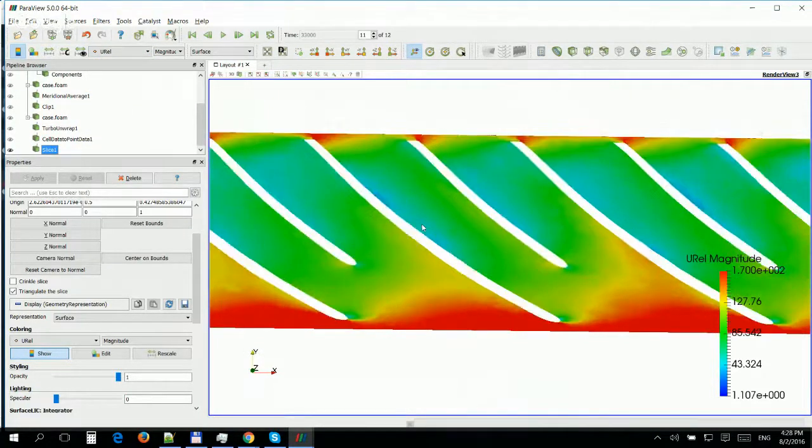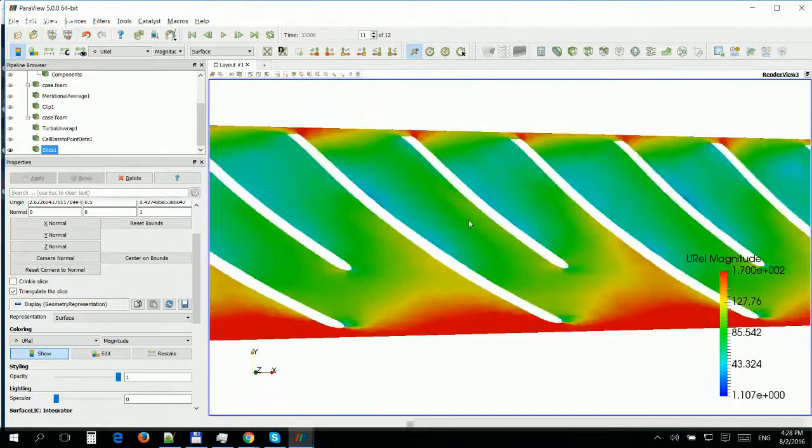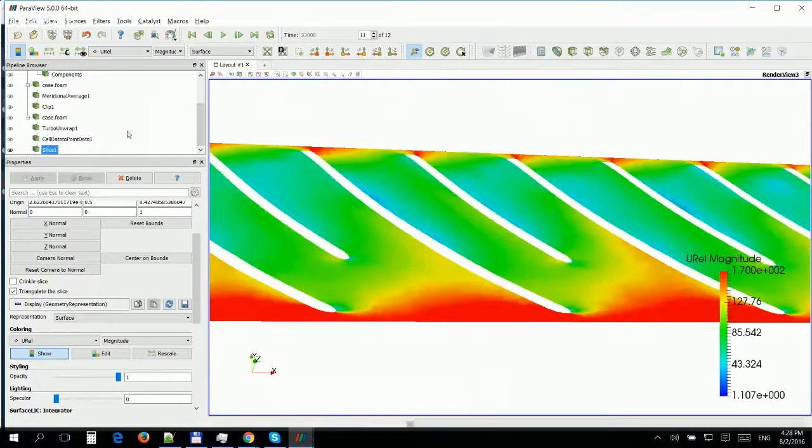Your impeller can be transformed to something like a hexahedron, and the intervals are like 1, 1, and 2π. In this transformation, for any quantity, any field, you can see the plane anywhere between hub and shroud. So this is important. This is, for example, the 50% plane between hub and shroud.